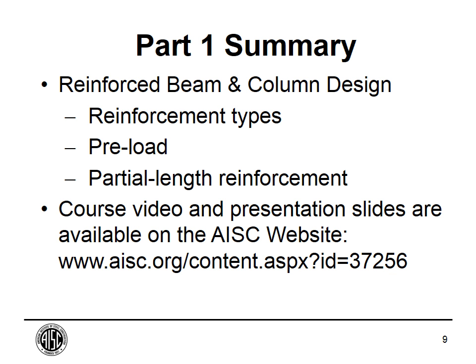You can't always remove 100% of the load that's on your structural member before you add reinforcement. In fact, a lot of the structures that I work on, industrial type structures, it's almost impossible to remove even a lot of the live load. So you end up with what I'm calling a preload on that beam that you have to account for when you reinforce the member.